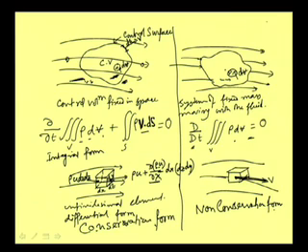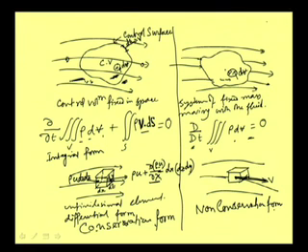So that way you can see that when our flow model is different, the equation that we ultimately get is different. But one point is that after deriving an equation, we can always go from one form to the other. From integral form to differential form we can go, and from non-conservation form to conservation form we can go, and from conservation form to non-conservation form we can go.